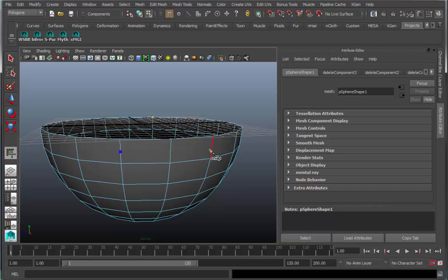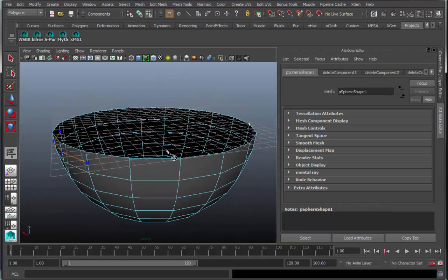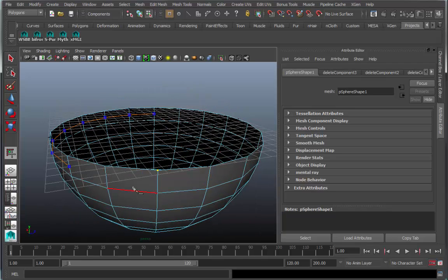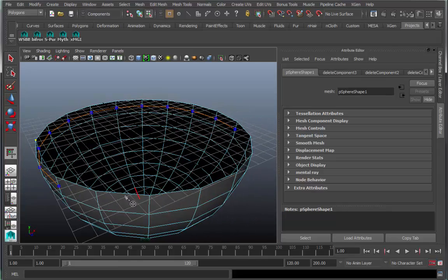Do not click over here. Make sure you go diligently one edge at a time. If you want to rotate your camera, that's fine. You can actually ease off the Shift key, go to your Alt key, and rotate the camera around. Go back to your Shift key and continue this journey of drawing a line exactly across the upper lip, the upper polygon ring that is the very top of this little salad bowl we've made.